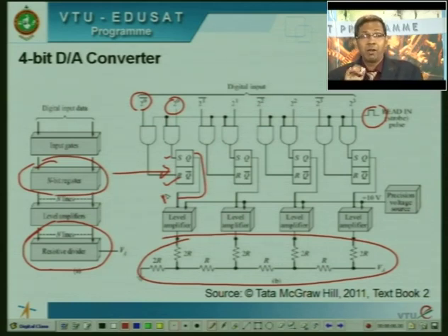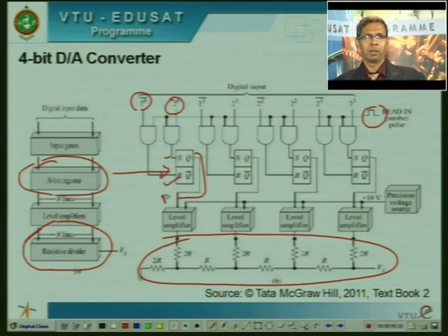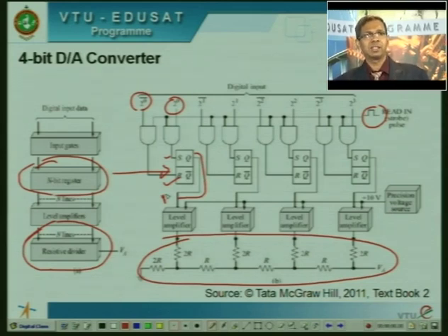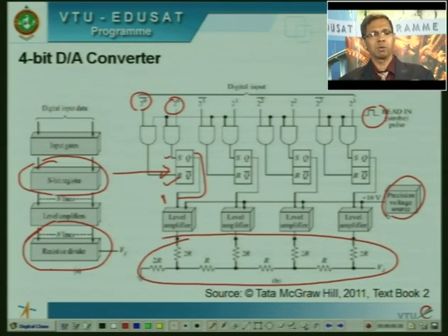At the end of the day, conversion requires to be very precise and as much as possible error free. The applied voltage, 10 volt, is the most important parameter here. So we need to have what we call a precision voltage source. It has to be at plus 10 volts irrespective of whatever current you draw, whether it is on load, off load, or shorted, whatever be the case.